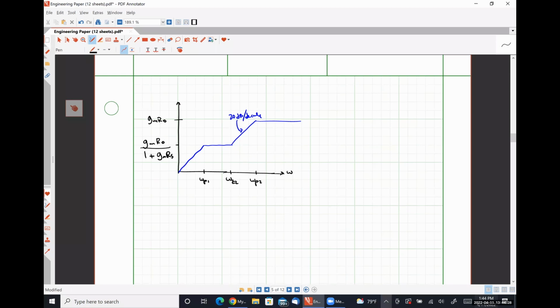That's why we have that hump, because there's a series of intermediate frequencies in our frequency response where the impedance of our capacitor CS isn't quite 0. So that our degeneration resistor is contributing until we start making that capacitor look more and more and more like a short circuit, and then we settle to our actual mid-band gain.